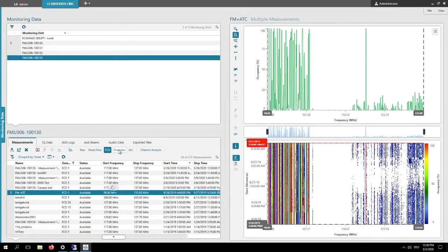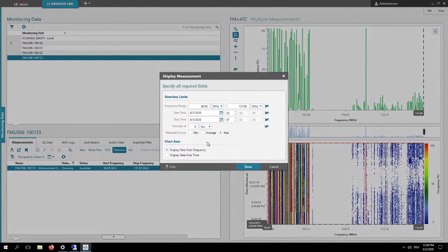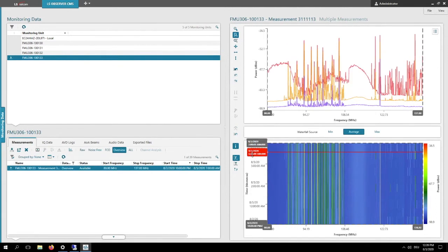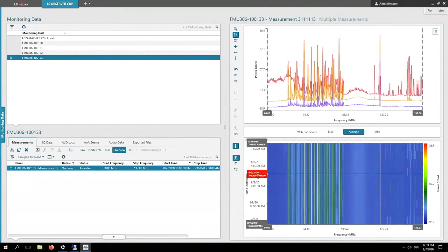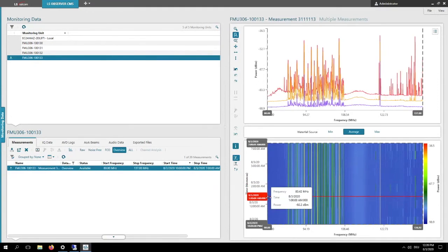Then you also have overview data. For example, you can set up an overview for a certain time range, for example for 1 hour, if I have here measurement over the night. Overview means you have the maximum, average, and minimum curve captured. Now for each hour one value. So you can see if I slide here through the time, you have one value for each hour, which is also a very easy to handle data type, very compressed.